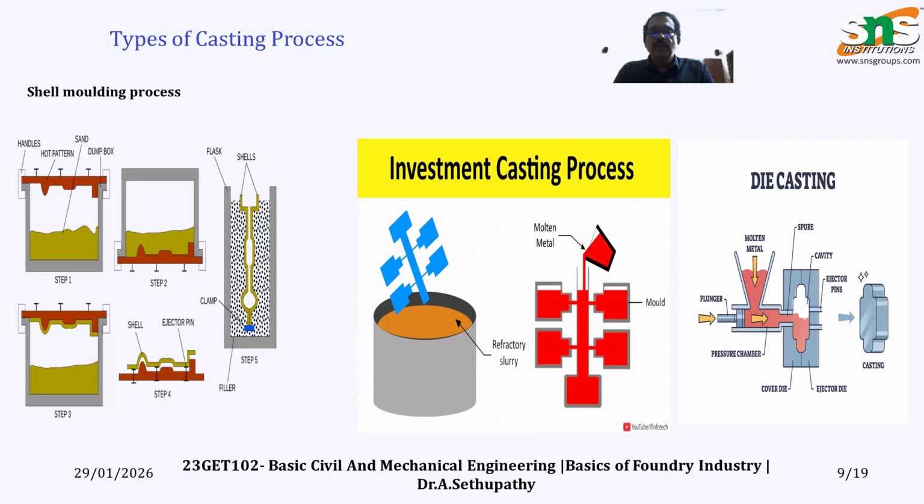After removing it from the furnace, the mold is heated so the wax inside is burned out. The wax is eroded from the slurry mold, so the inside wax is fully removed and only cavities remain in the ceramic coating.